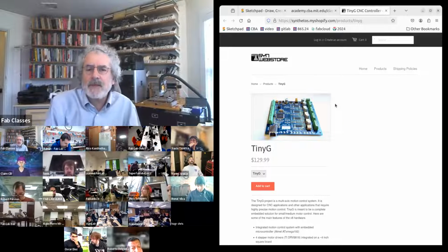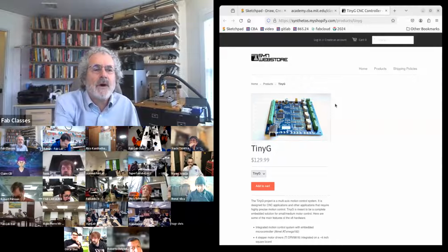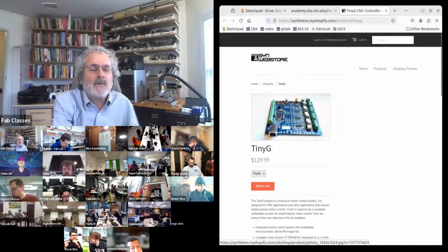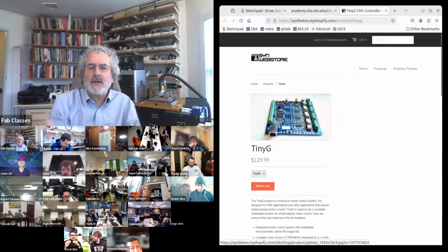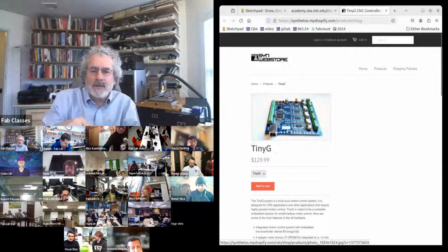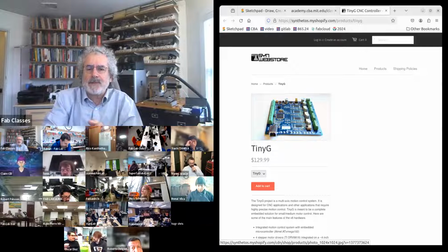This is a good example of if this does exactly what you want, it's really convenient, but it has two problems. One is you can't add one more motor. You're limited by what's on the board. And the second one is the G code doesn't understand the machine. It's just a general purpose code. So in this board, you need to explain how the axes relate to each other.